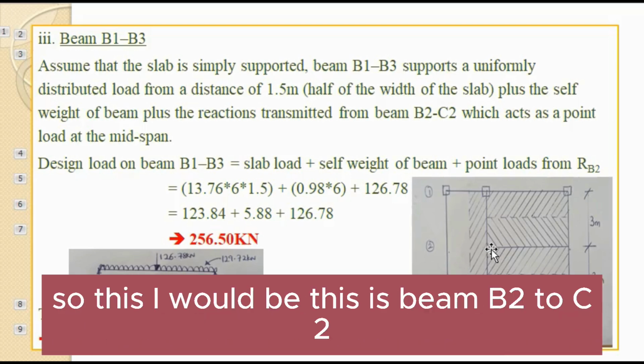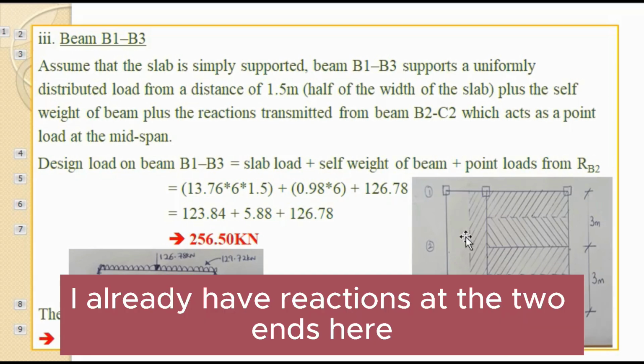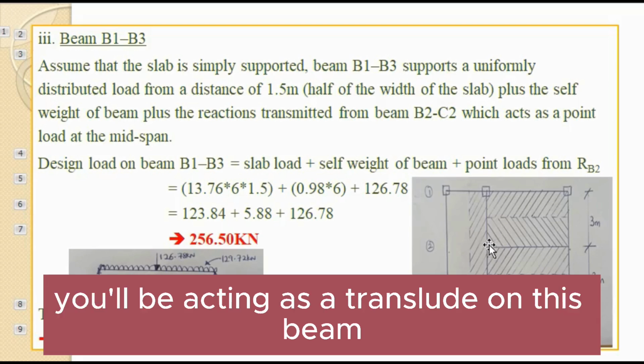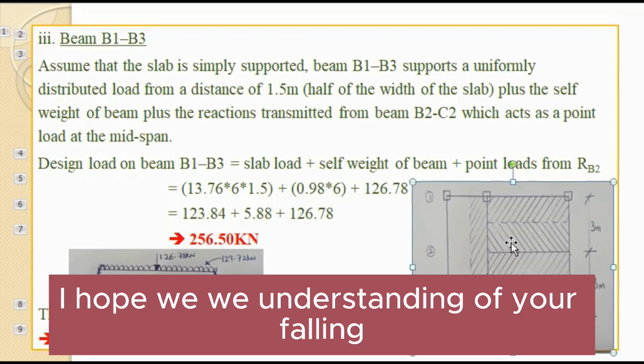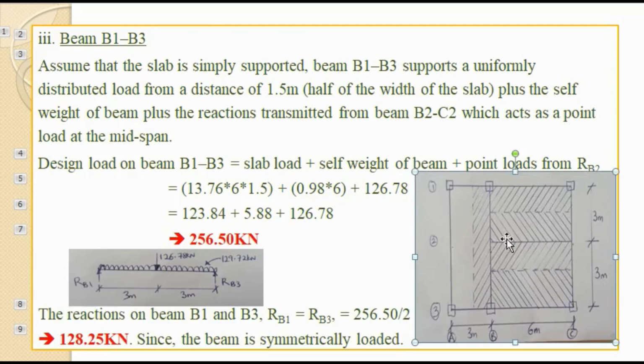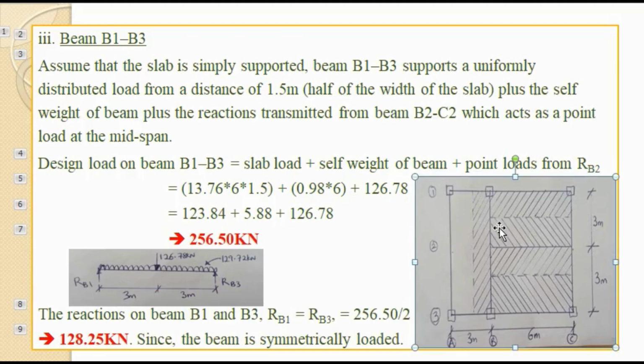So this is beam B2 to C2, and we already have reactions at the two ends here. So the reaction at this end will be acting as a point load on the beam we are considering. I hope we are following. Okay, so that is what it is.